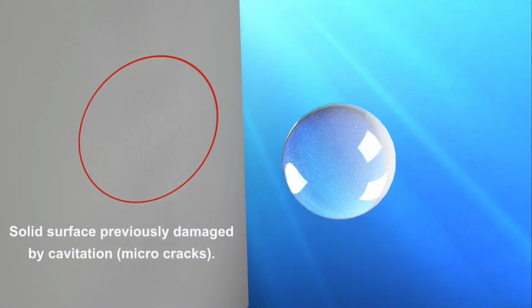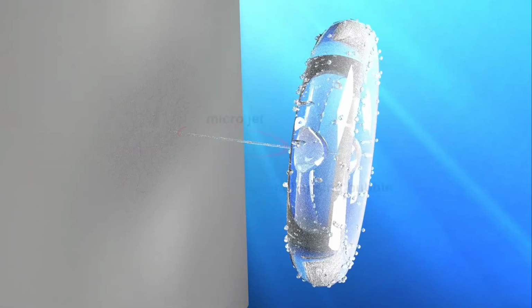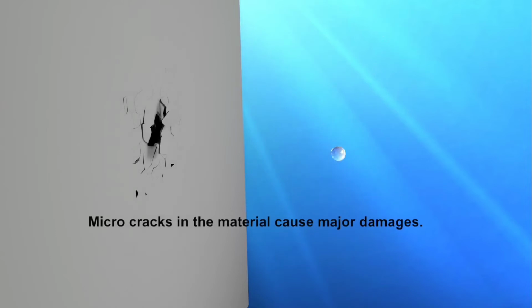So now you may be wondering how a bubble can damage a metal. The bubble can damage the metal through its concentrated impact. Even high-strength material can be damaged by the implosion. It releases energy in a very short time, concentrated in a very small spot. If the microjet hits a surface, it damages the material by localized short-term overstressing of the material.